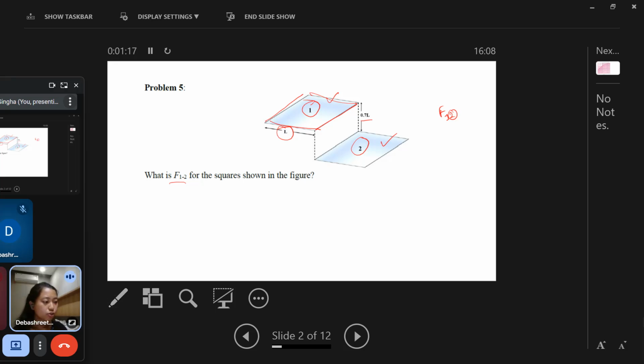So far, whatever we have discussed in the previous lectures, the view factor problems were solely based on the area and on the intuition, I mean how much the view factor should be from one surface to the other. Some are 1, some are 0. Some due to symmetry are 0.5. If there are two surfaces and they are symmetric to each other, then we can consider 0.5.